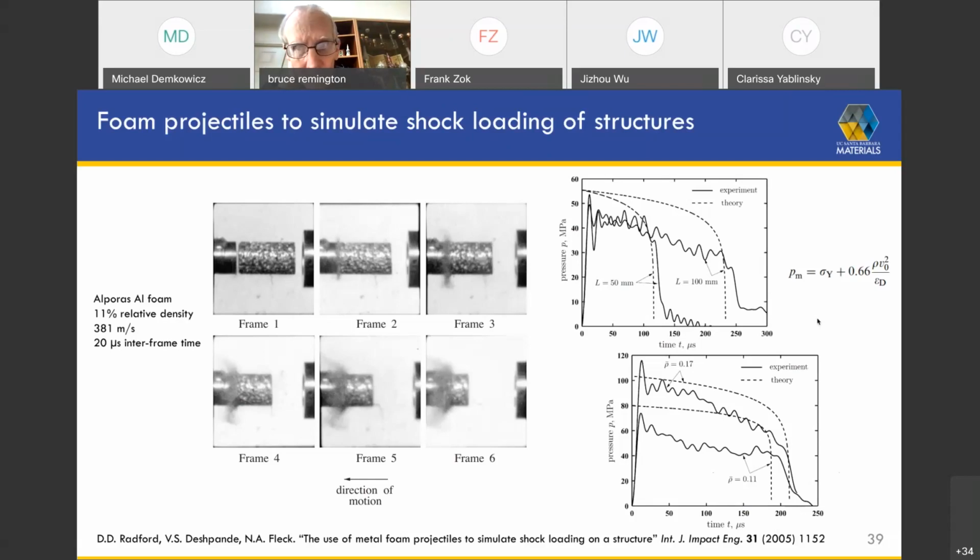I don't see any other questions showing up in the chat box, so I'm going to ask one more of my own. Oh, wait, we got one. So let me read the one from the chat box. From Jalen James, I have analyzed stress versus strain curves of split Hopkinson pressure bar tests in my research and have found that a different response can be obtained from nominally similar experimental runs. What contributes most to this varying response in stress versus strain for SHPB tests of nominally similar experiments?